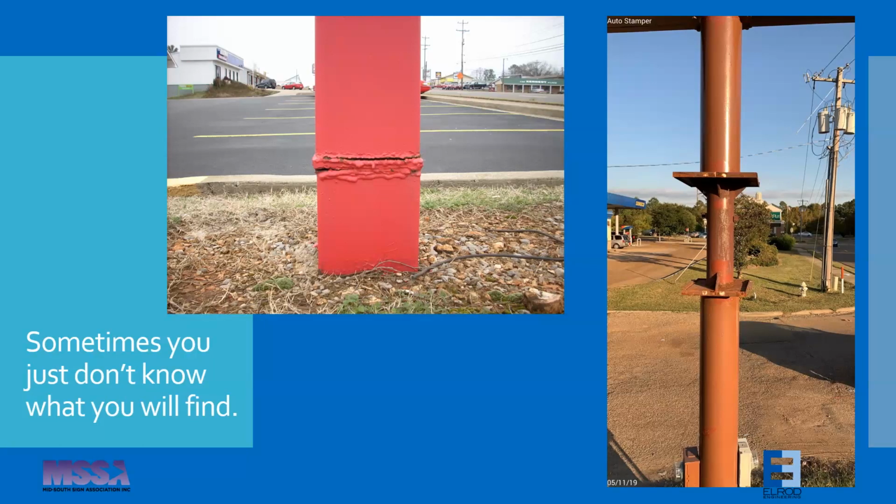The one on the right was from an inspection that we did on a client site where they had an adjacent landowner ask them if they could put a secondary cabinet on the sign after it was installed. Our client said, sure. When we came out to do the inspection, we took the secondary cabinet off to look at the pole. Turns out they not only had put their secondary cabinet on, but they cut the pole, put in a smaller diameter pole, welded things back up, and put their cabinet back in place. Obviously, that is not per design. That is significantly overstressed. Fortunately, nothing happened to it, but it was fixed and taken care of, and it's a much safer structure now.